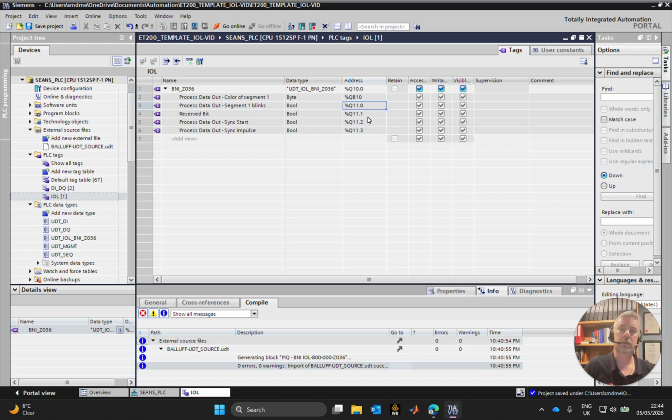Now this is incorrect, wholly incorrect. All this data here needs to fit into the same byte. That's what was indicated in the PCT, in the port configuration tool, that we were running with 8 bits of data, and all this data must fit in it.